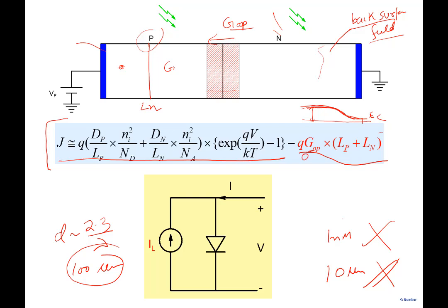Because if you have a hole and you have a band diagram like this, note that a hole has difficulty going down in energy. So you are almost creating a barrier, right? So you need to do something in this region so that you get a band diagram like this. So a hole which exists here cannot go towards the contact and recombine. You have to prevent holes from going to the back.